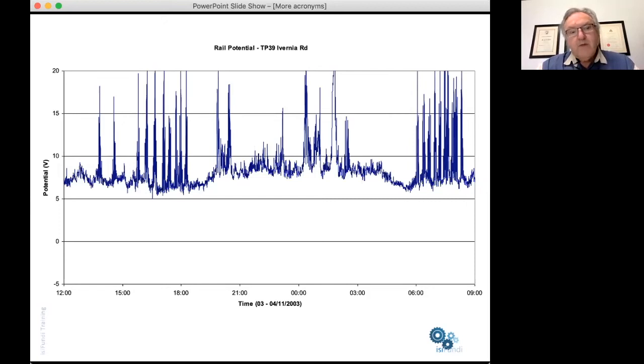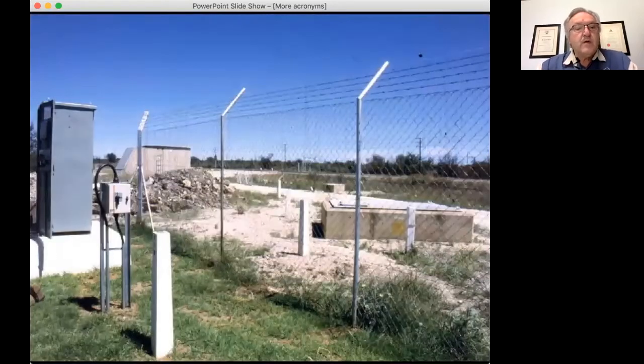There may be requirements to drain current back to the rail, even when the rail is not negative with respect to earth. And in that situation, we can use what is known as a forced drainage unit. In other words, we've incorporated a power supply into the connection back to the rail. And this unit is what we have in this diagram. On the left-hand side here is the power unit.